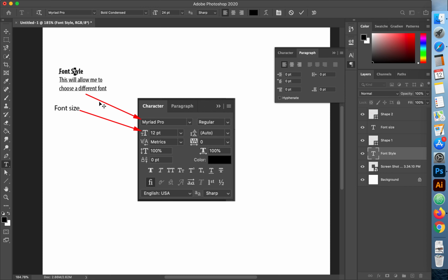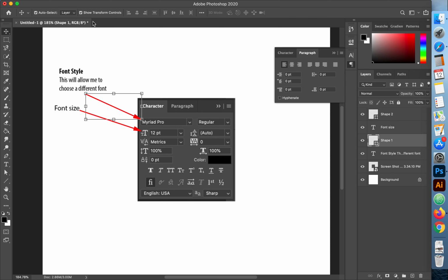If you have to adjust the arrow, you need to be able to click on the arrow, and you'll notice I click on it, nothing happens. I selected the shape, that's fine, but nothing happens here. If I click on Show Transform Controls, that'll give us the ability to move this. It's going to shrink it or make it bigger.